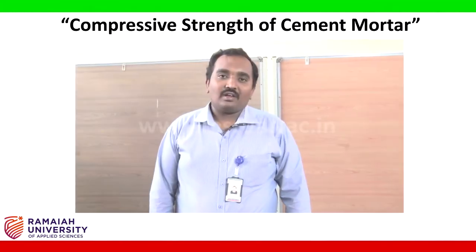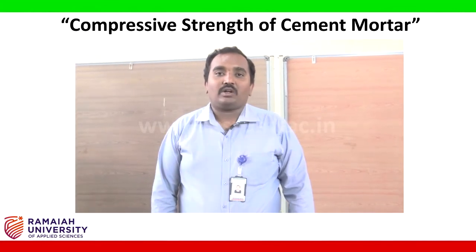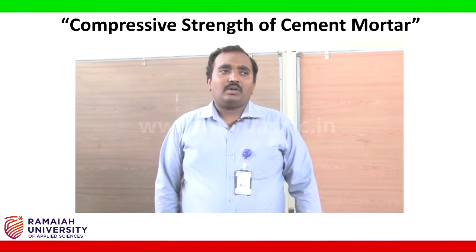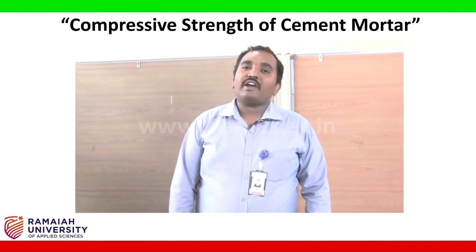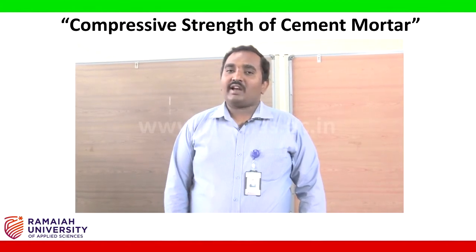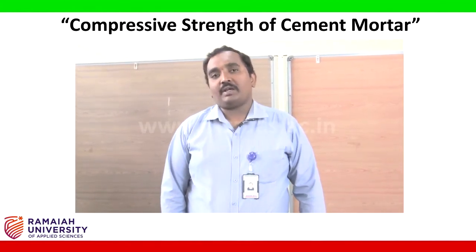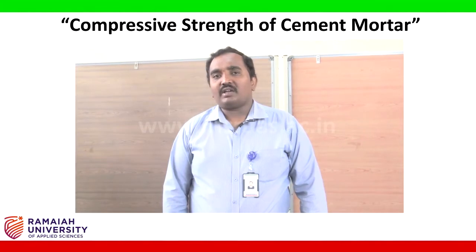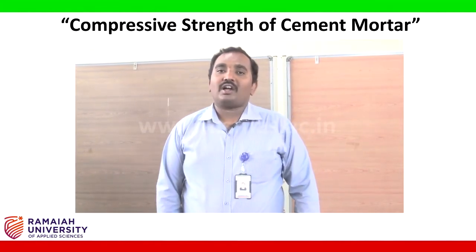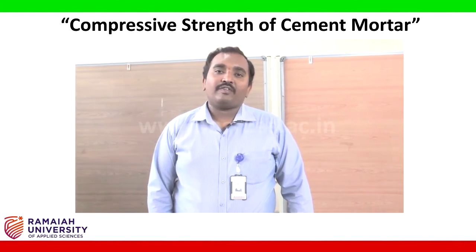Hi students, now we will be doing the experiment on the compressive strength of cement mortar cubes. If you have come across the different grades of cement, like if I take up OPC, you have 33 grade cement, 43 grade cement and 53 grade cement. What does that number indicate? The number indicates the compressive strength of cement mortar cubes at the end of 28 days of curing.